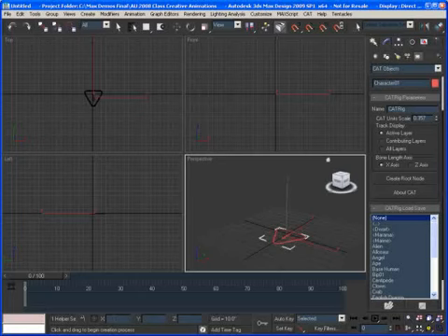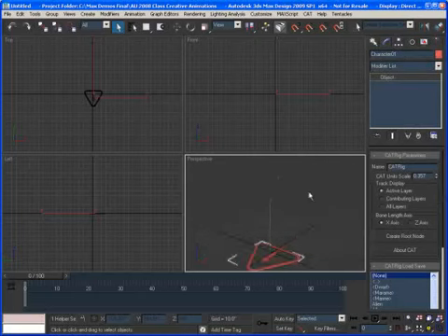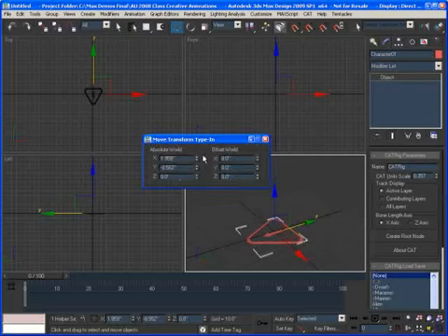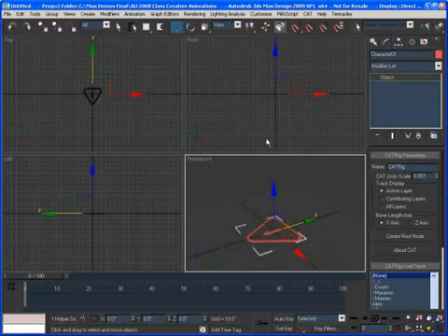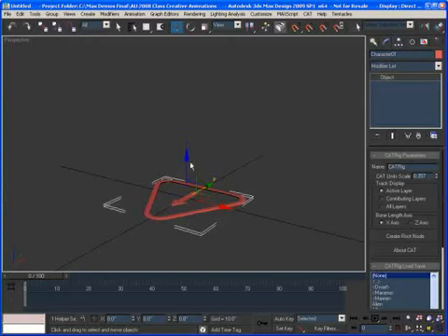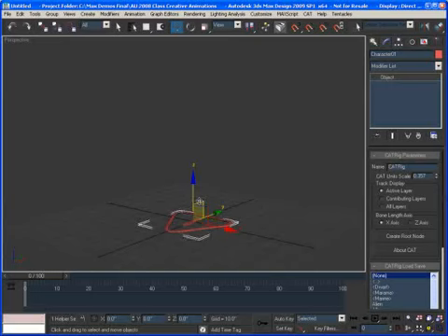So now what I can do when I've got a CAT parent inside of the scene, I can go to the modifier stack, and I have access to some of the tools that CAT offers. I'm going to move that here. I'm just going to place it at the center of the universe here, like that. And I'm just going to maximize the viewport so we can see. So we got a CAT parent. We don't have any type of rig on top of this CAT parent yet.